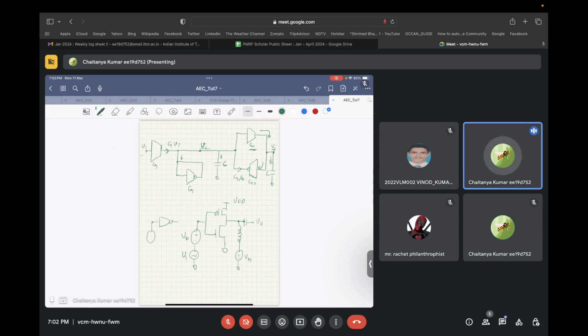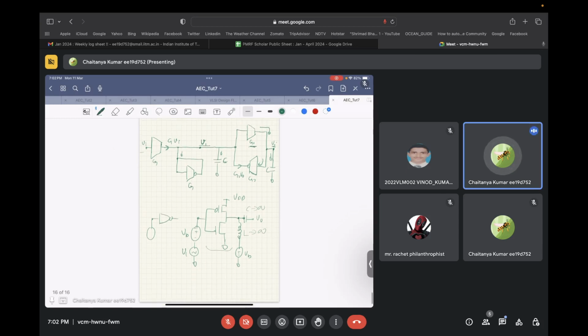So in this case, at DC, of course, let's say this inductor goes to infinity and this capacitance goes to infinity. These are very large values. So this inductor is just for representational purposes. We will remove it as we progress in the circuit. So in that case, this particular inverter will behave as an amplifier, or as a transconductor.